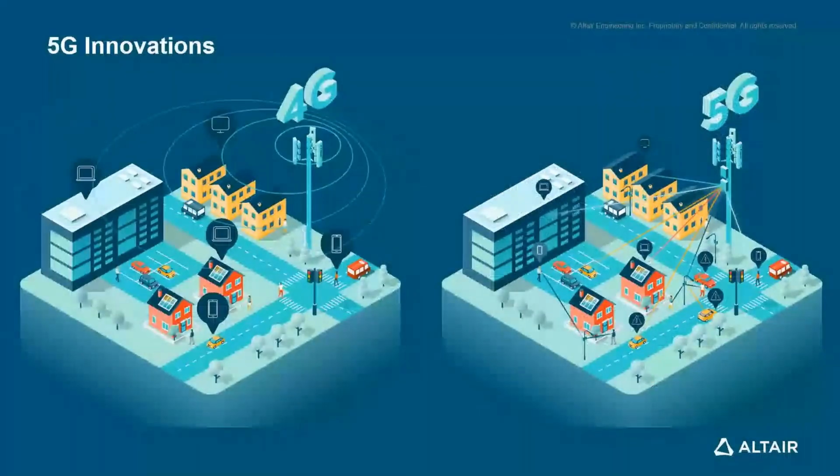So to put things in context, when we compare 5G networks to 4G networks, we mainly know that in 4G networks, the different users are served by normally a base station sector, whereas in 5G networks, the main difference is that they provide higher capacity by using individual beams per user within different sectors, but also by adding small transmitters and cells that could be mounted, for instance, on lamp posts and others to serve the local traffic.